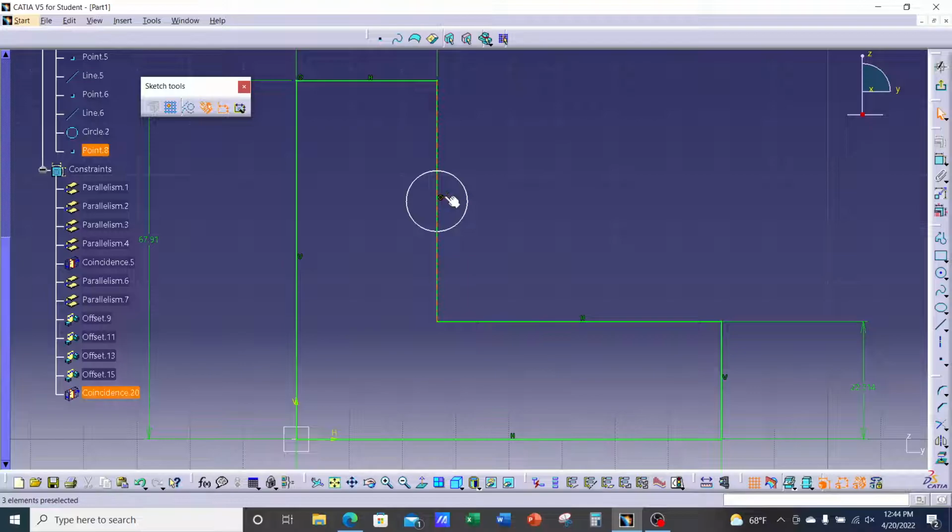And notice we have that constraint, and I can take this circle. Notice I'm missing a diameter or a radius constraint. Also, I can grab the point and I can slide it up and down, but not left or right. So just to show you that we do have, I'm just clicking in space to deselect. There's our constraint. Center lines up with the vertical. All right, so now we need a diameter or radius. So I'm going to add a dimensional constraint.